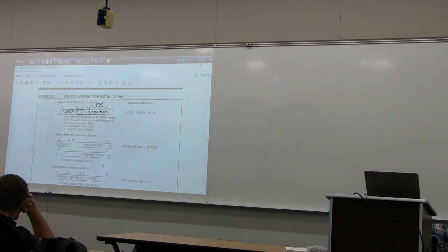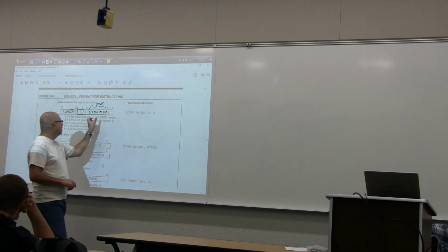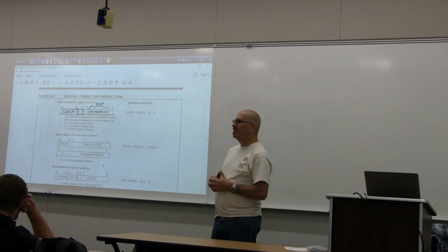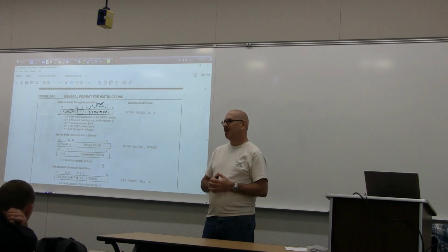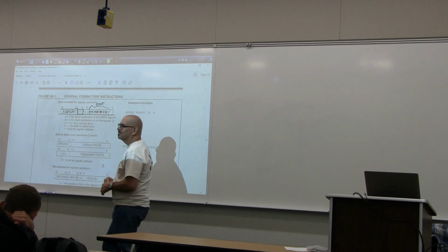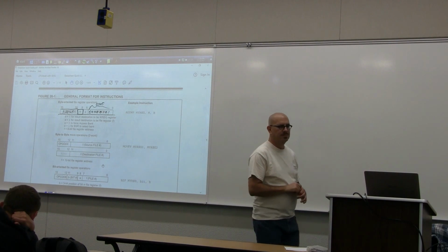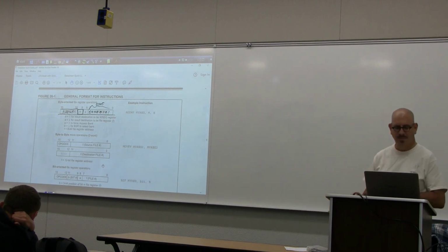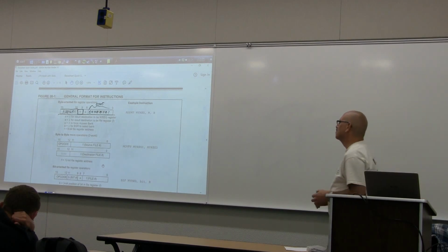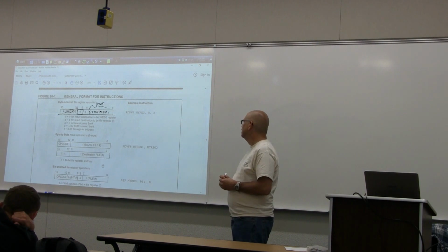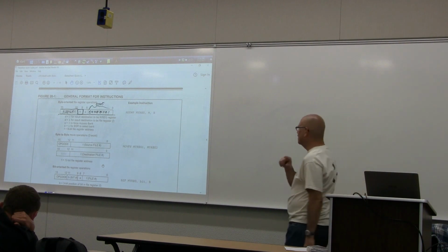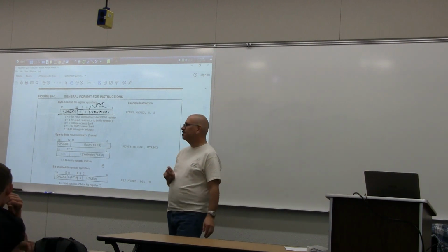So the opcode says what you want to do. The file register tells you one of your operands. If you need a second operand, it's always the WReg. And then the destination bit says where you write the result: back to the file register or into the W register. We're going to ignore the A bit for a moment, so don't worry about that one. All right, so ponder that while you stretch your legs for 5 minutes, and then we'll start coding some instructions.